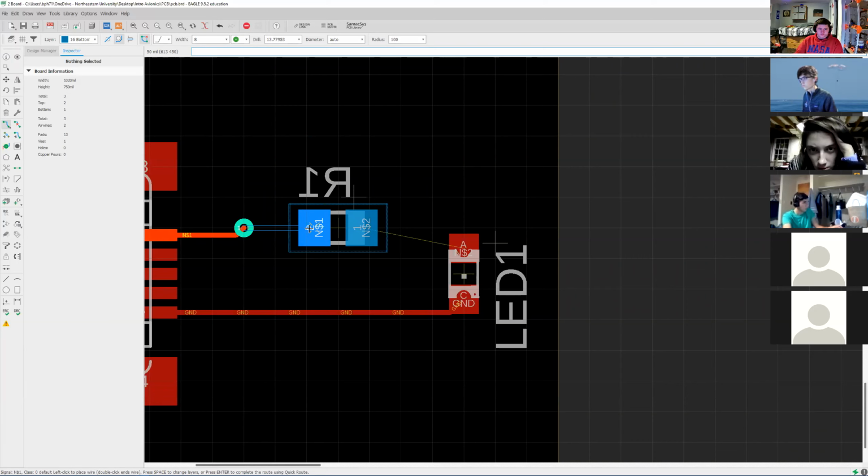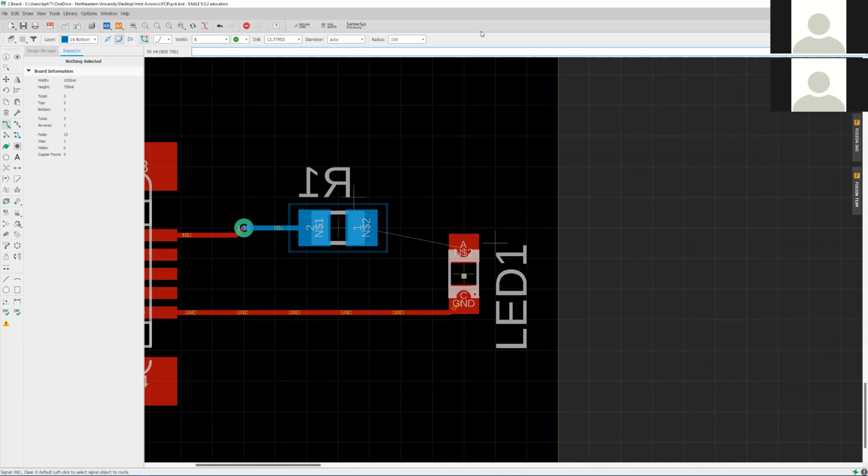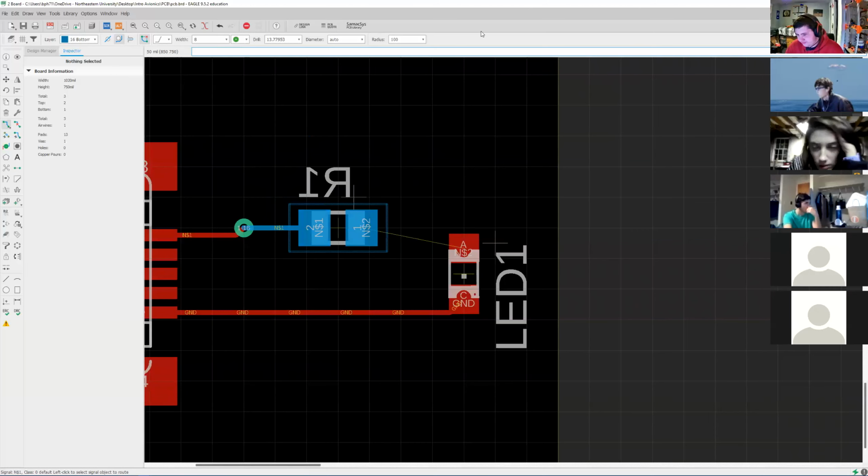Oh, I think my resistor is just upside down. Is your resistor red or blue? Okay, now it's blue, but my via is still not. Oh, Molly, I just saw you asked a question. Are you still having issues? I figured that out. Okay, cool. But I didn't get the ground all the way, so that might be the problem. It shouldn't matter. If you haven't completed a net for something else, Eagle won't care if you go on to work on another net.